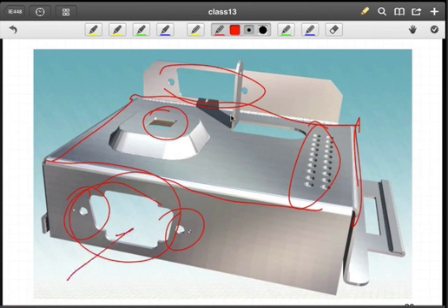For instance, if I have a problem with this stamping operation in terms of location, it may be impossible to repair that because we've already removed the material. However, if I have a problem with the geometry of an individual feature, I might be able to rework that individual feature and create the necessary geometry as long as it's in the right location.